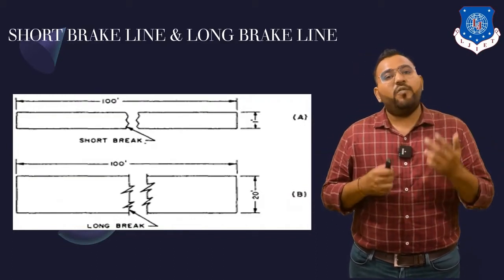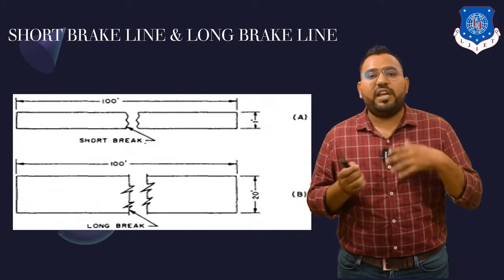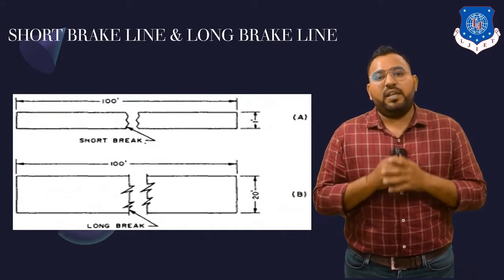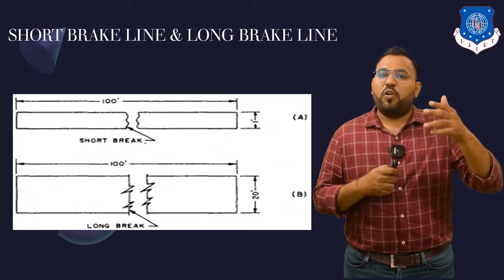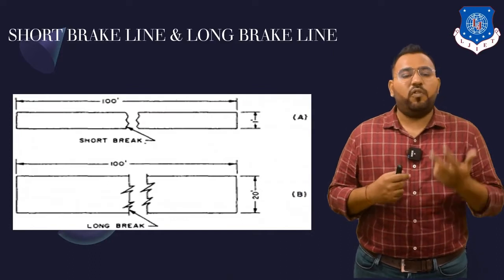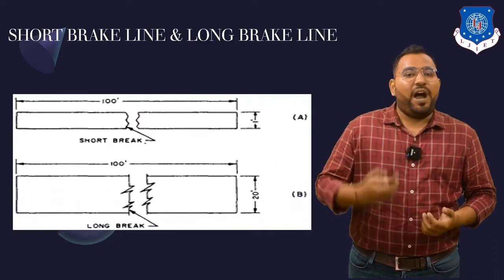In the same way, from a short break you will get to know that this is actually a very large object which cannot be drawn in the drawing book, but for simplicity we have given the wavy pattern in the form of a short break. Okay, so a short break is used for showing a large object, and a long break is used for showing a very wide object.